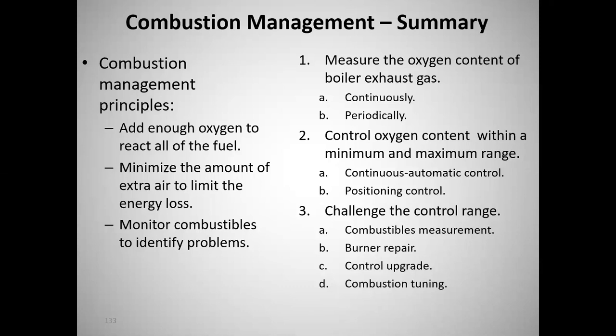And to purchase a combustion analyzer, I've got several combustion analyzers that we use. Someplace between $3,000 and $15,000 will get you a combustion analyzer. The $15,000 one's going to measure more stuff and probably be better. But for basic oxygen, you can get a handheld portable instrument that'll do it for probably $3,000. Anybody operating a boiler should have that capability.